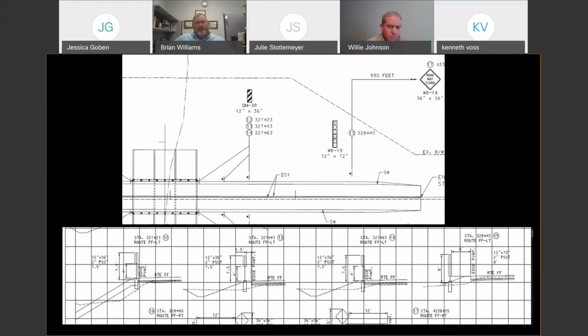Okay. And again, as I flipped through the plans, I saw the signing sheet, and then looking at the signing cross sections. Well, my goodness, sign 13. We've got defined ditches cut right here. We've got potential conveyances where new fill is going to meet the old, and we're going to actually have some ditches here that we need ditch checks in. So we have to stop and think about that as design. Where are we going to have ditches? Where is water going to actually channel and provide ditch checks in those areas?